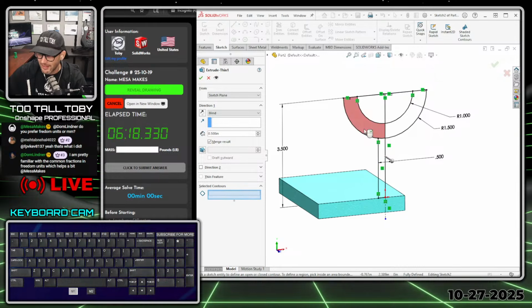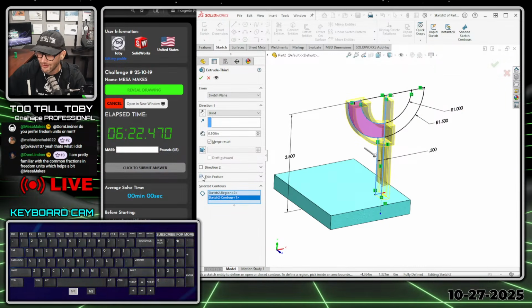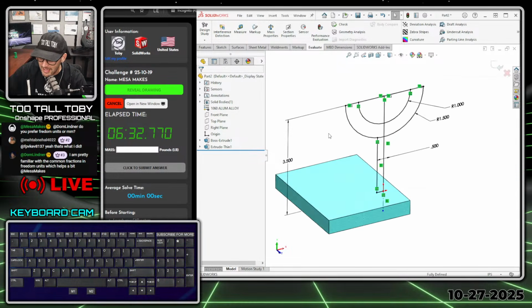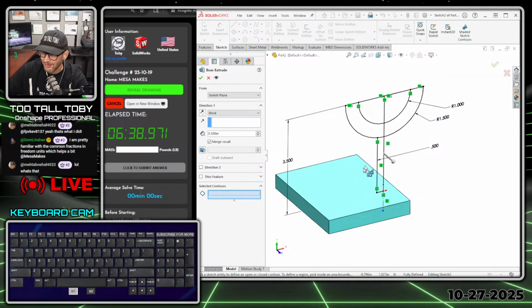So let's see if that actually works. So I click this. No. Still checking it on. Uncheck it. Check mark. There we go. SolidWorks being SolidWorks. So instead of editing that feature, maybe what you want to do is Control Z, get back to the point where you're in the sketch, and then S key extrude again, and then you can go through and pick these contours.